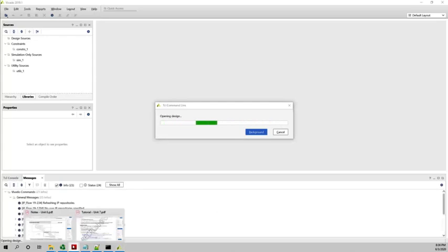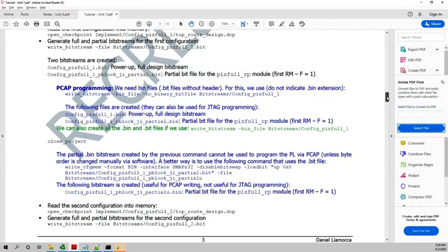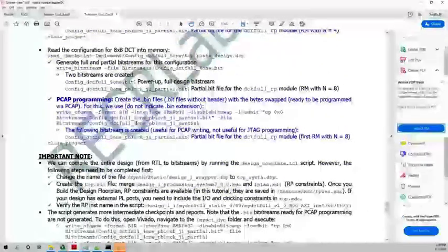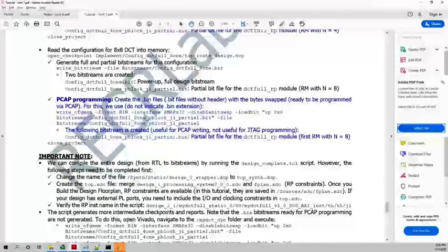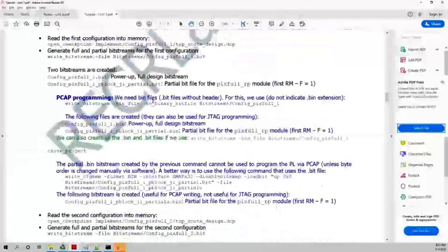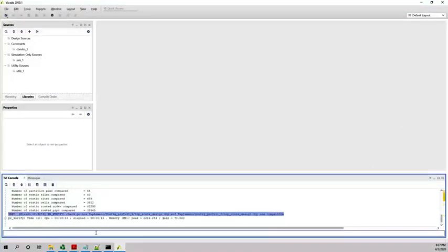It's going to take a little bit of time, but we're almost ready. Just let me check something just in case I'm missing something. Okay. Let's do it in our own way. So luckily this should tell you here they are compatible. These two designs are compatible. If they are not, you might get the bitstream, but it's not going to work, I guarantee you.